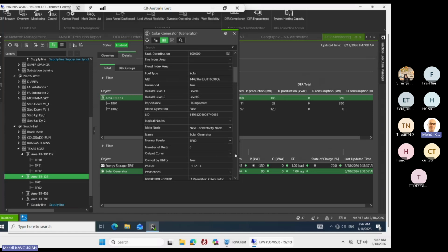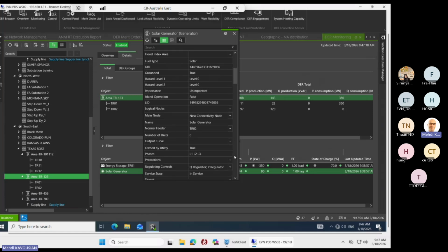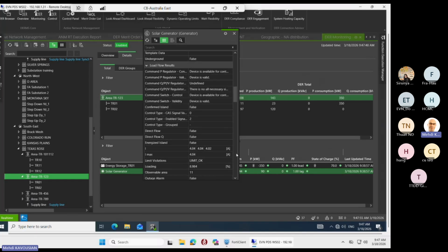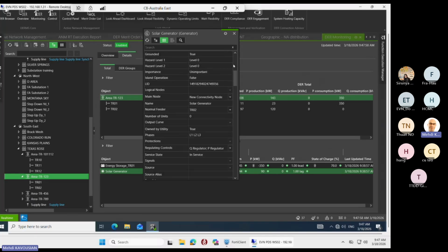Even for solar, you could have a curve, but normally we don't use it because solar is generally linear. There are some other things that it uses, for example, the temperature. If the temperature is above a certain value, the solar panel usually loses some efficiency. So if it's more than 25, it also uses temperature to reduce it. If your temperature is 35 or something, it just reduces that as well. So it is explained in the functional specification, but it's not just radiation, yeah. It could be multiple factors, temperature as well. Okay.